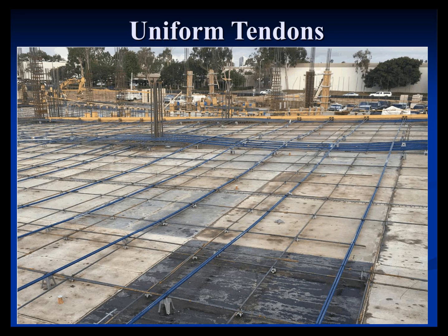I don't recommend counting strands or counting rebar. It's more or less look for the oddities, look for the kinks in the strands, whether it's a vertical kink, which can cause localized uplift forces or blowouts, or a lateral kink, which can create a lateral force in the slab, which can usually cause cracking and blowouts as well, which I'll cover in a little bit. So basically, the general concept is always to have uniformly spaced, gradual profiles vertically and horizontally.